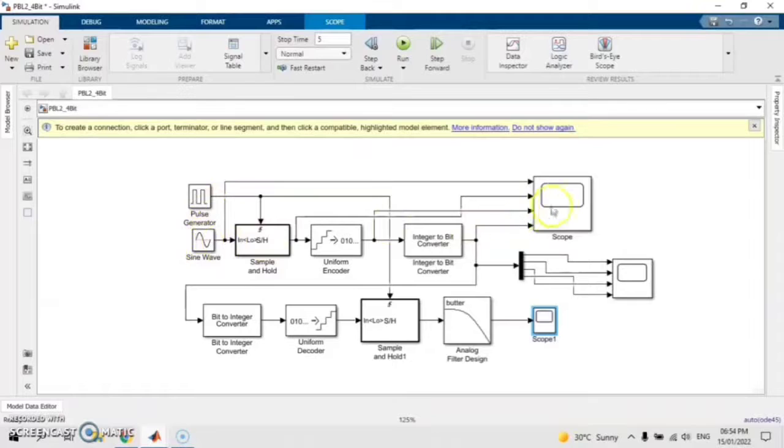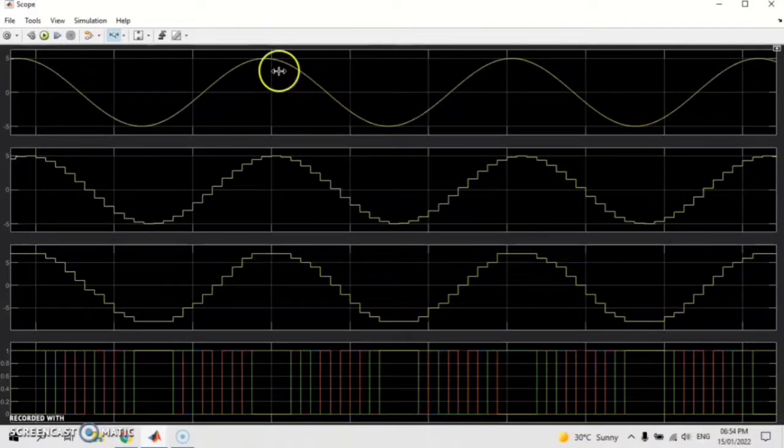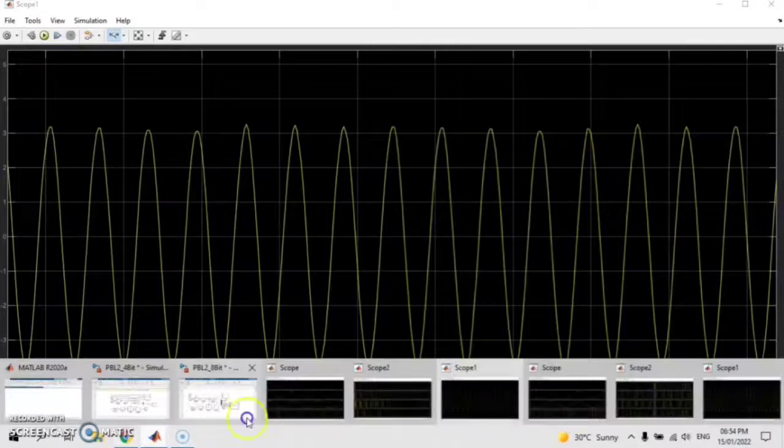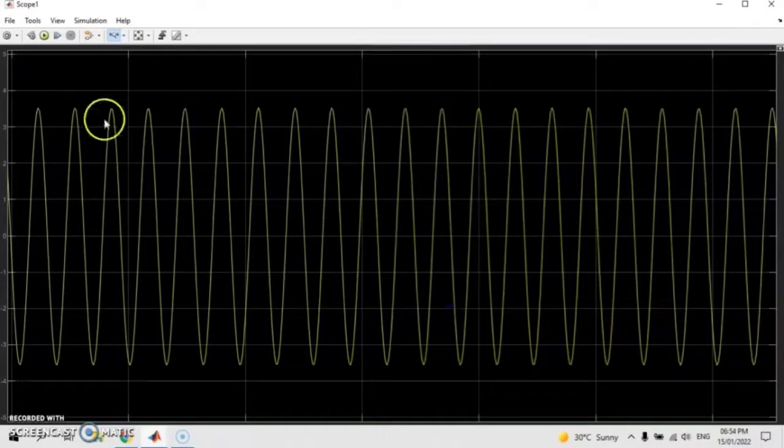Okay, this is the signal that we have used here, about 5 here, but we have some losses, and in the decoded signal the amplitude is lessened a bit, but the frequency is still the same. So we conclude that the more the number of bits, the better the decoded signal, and it's closer to the input signal that we have given. So let's check here, 3.2, and for the 8-bit one, we got about 3.5, which is higher. And that's all for part B. Thank you.